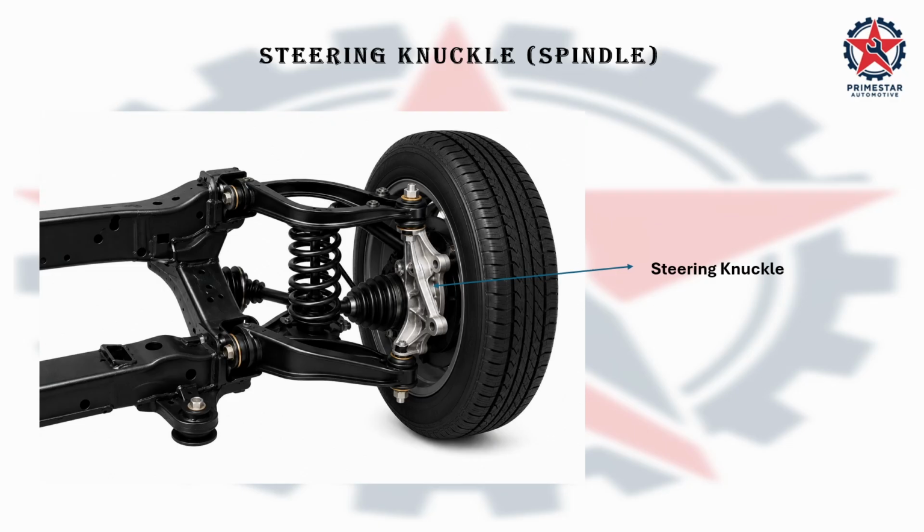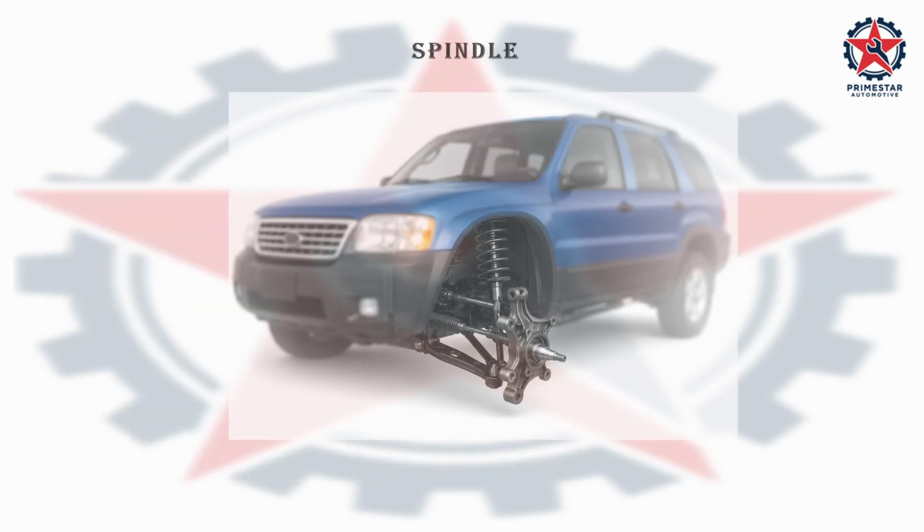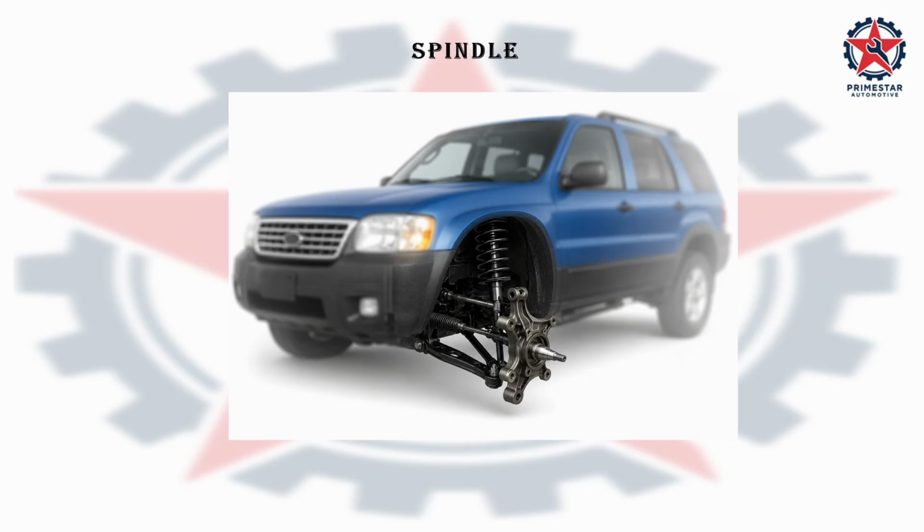The steering knuckle is the component where the wheel hub and brake assembly are mounted. It also connects the steering and the suspension components together. Think of it as the backbone of the wheel assembly. Many important components are attached to it, allowing the wheel assembly to work as one complete unit. Its job is to support the wheel assembly while allowing the wheel to rotate as the vehicle moves forward, reverse, and turn left or right when the driver steers.